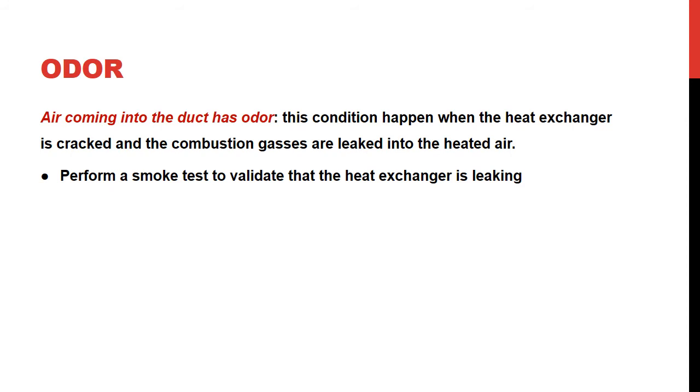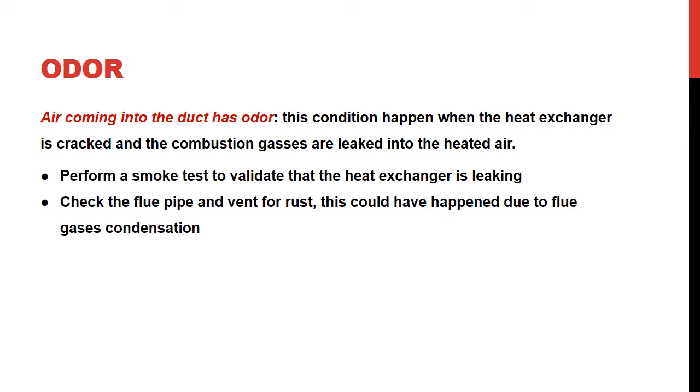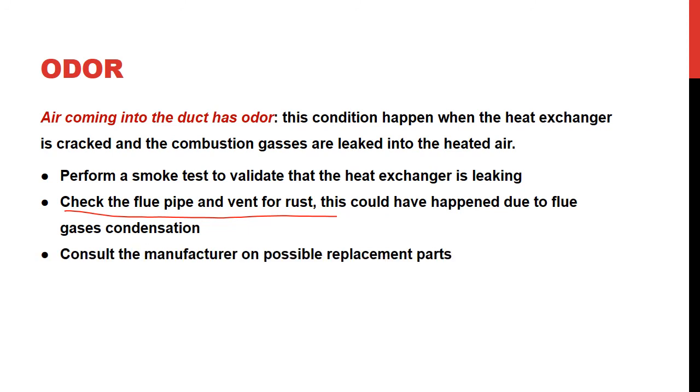visually. A smoke test is very good to know that it's not leaking, and you can also do a pressurized smoke test. Check the flue pipe for rust. If that's the case, most likely there is some kind of rust going into your heat exchanger, and probably the temperature at the flue pipes is very low. So that's another area to look at.